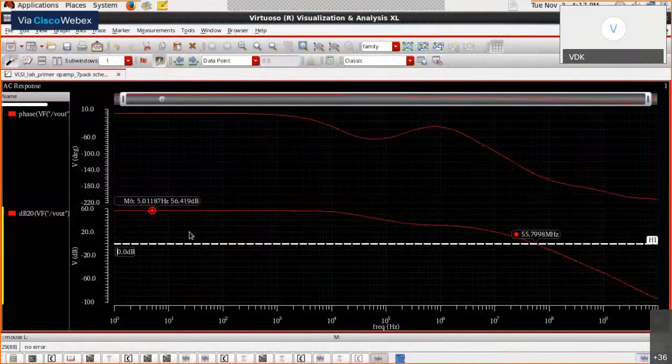For each bin, we generate all these parameters as functions of gate to source voltage, for different values of source to bulk potential difference, and for different values of drain potential difference also. I have a huge set of data, so I can look up, and if I find that I need to generate a little more, then I generate it. Did I answer the query?